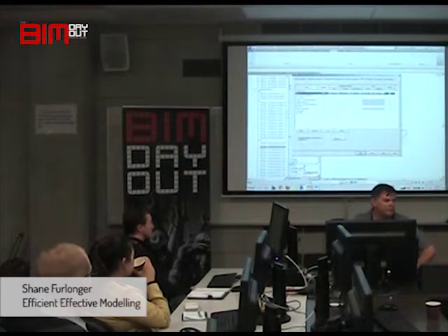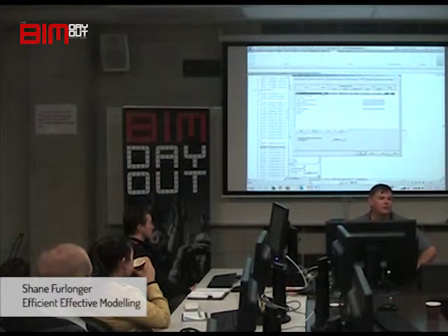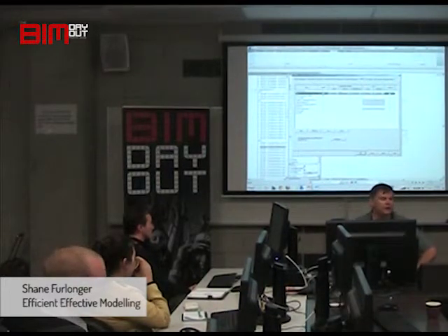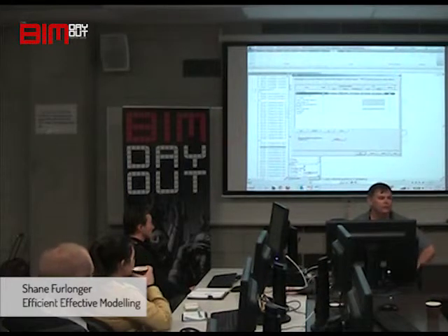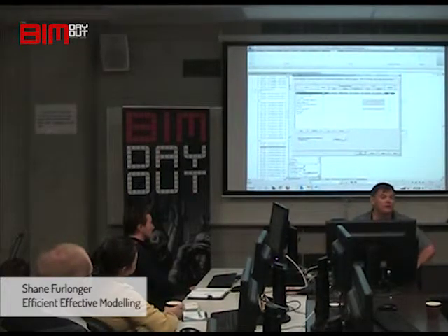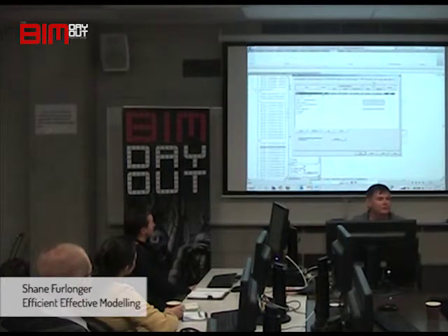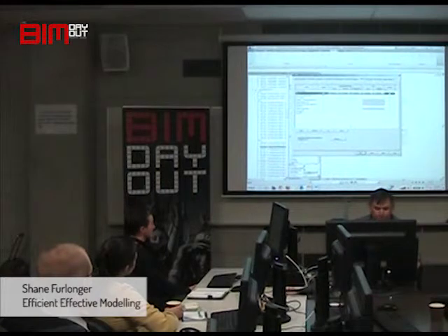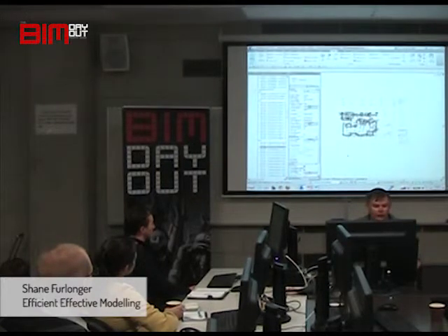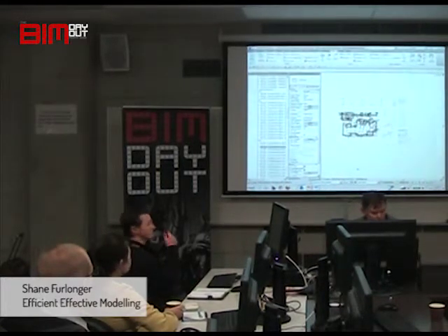So you can set up different filters for each of those items, and then when you lay that out on your floor plan, you get your fire strategy straight away without having to do anything stupid. It's really simple and quick. You don't have to go drawing lines around your page saying this is a firewall. It just does it for you. So filters are really powerful. Use them. Right, that was filters.